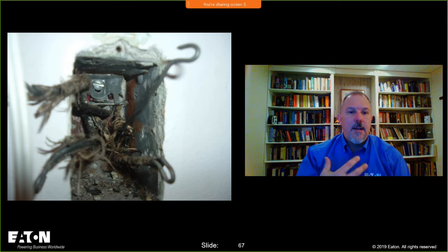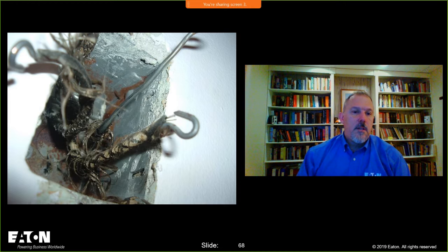And when we took everything out, that conductor was on an outside wall. You can even see the rust inside behind that box. It wasn't very pretty whatsoever. But there's a better picture of it, and you can see how the insulation just came right off of those conductors.